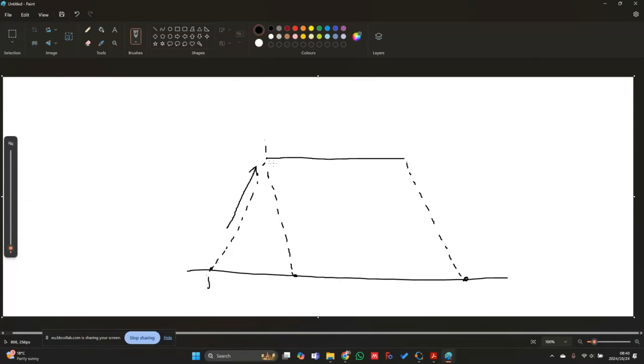And in my case, it would make sense that I want to rather focus on the forces going upwards onto the platform body over here. So it would be best to rather use point I for these 2 points A and B, and then use point J as the grounded revolute points that we have over here. So then all of the vectors will point upward.